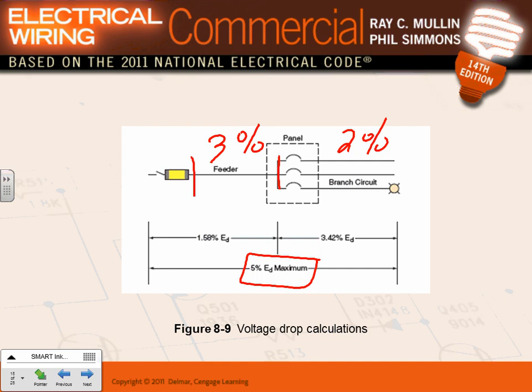That's how we divide them. This is how engineers divide them almost always. So if I have a voltage of 208 volts here, I can have somebody with a calculator get me 0.95 times 208 volts. I have 198. I can have 198 volts at the equipment. Can you guys see that? I started at the service with 208 volts. I can only lose 5%. When I reach that load, I'm only down to 198 volts.